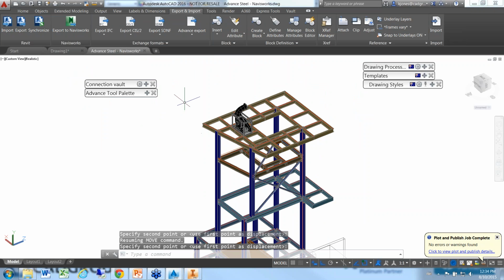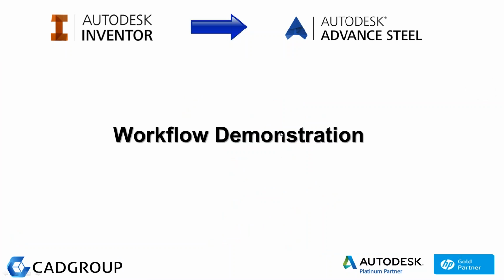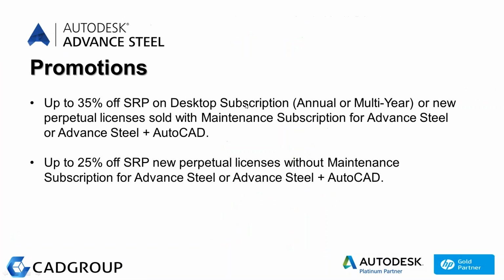Okay, so it obviously doesn't go bidirectional back through to Inventor, and it's not associated with the Inventor model. So if that blower does change, the SAT file hasn't changed, so we'd have to replace that particular file using the same process again. Okay. So that concludes the Inventor workflow there, guys.